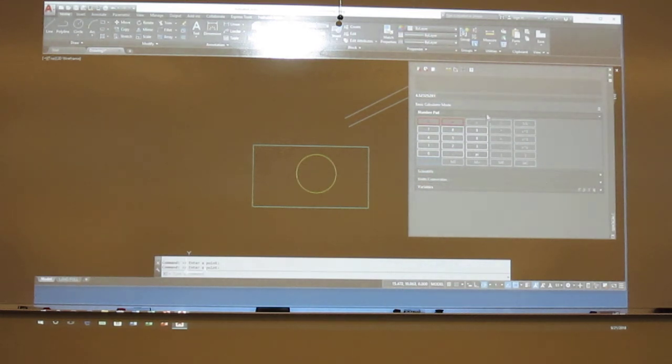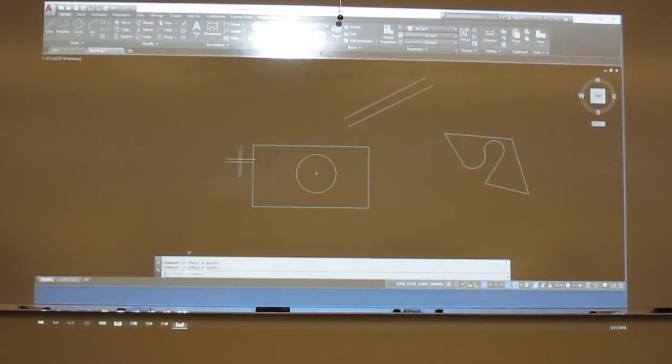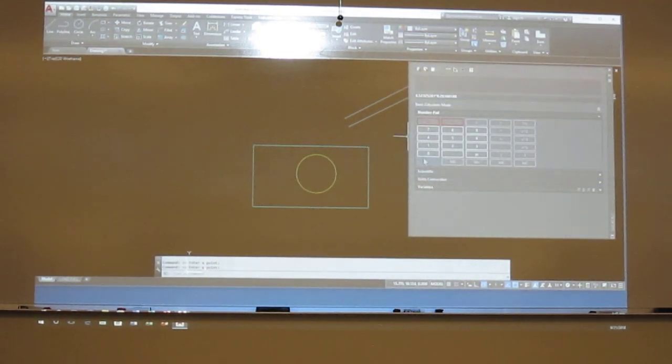Then I'm going to click on there and I'm going to say times, and then go back and re-hit the distance command, and now I'll do, because this is a rectangle, base times height, this area, right? Click there, and then equals, and there it is. There's my area, 37.6. So this is kind of nice in that it can pull info out of the drawing and use it right inside of the calculator.